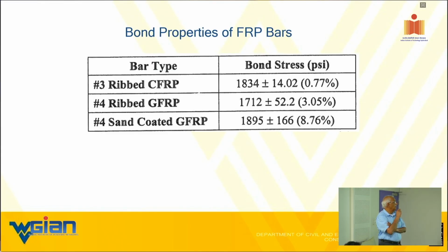For that, we have to keep the gauge length in the range of 40 only. Again, remember, why am I talking about 40? Where did the 40 come from? The bending issue is what is making it a 40 number. I'm not saying there'll be zero bending. I didn't say that. There may be some bending, but its influence is minimal. To reduce the P-delta effect, yes. That's right. Exactly right.